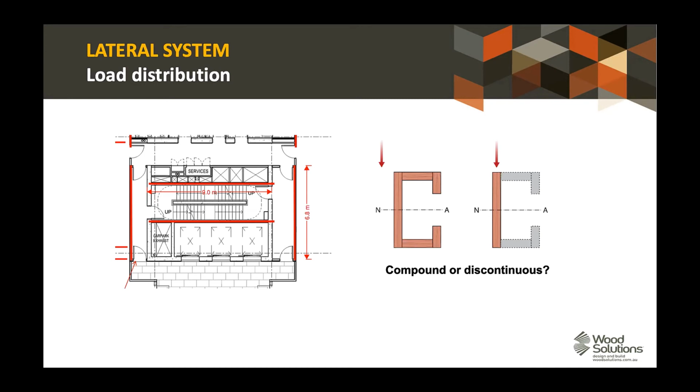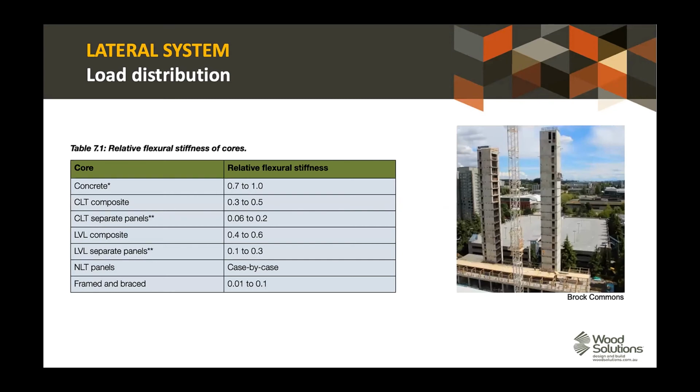There is detailing, and there are practices around the world where they make the core out of concrete or something similar. This is Brock Commons, not a lightweight timber frame solution, but a really clear image of cores and timber. And we do have the relative stiffness to think about. If we have a concrete core in our building, there's a good chance it will attract the vast majority of the load compared to any timber bracing elements that are in the mix.